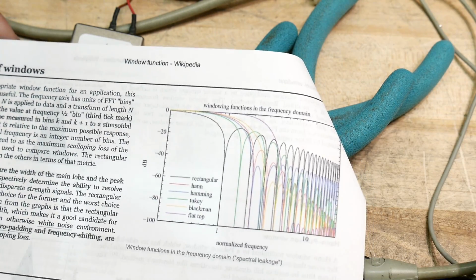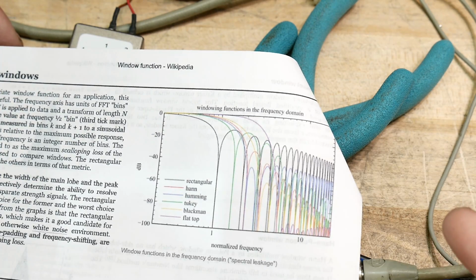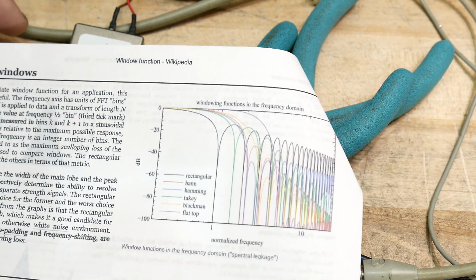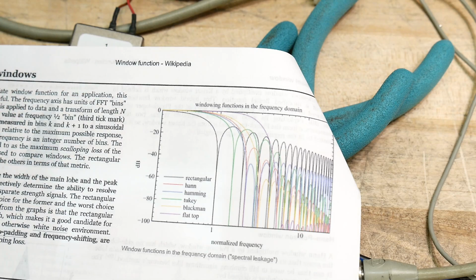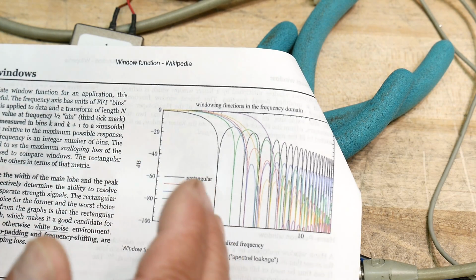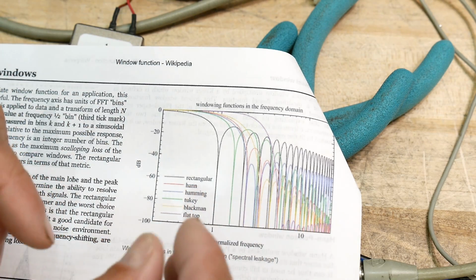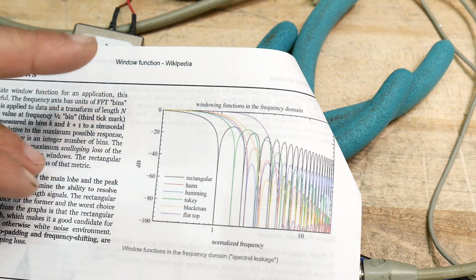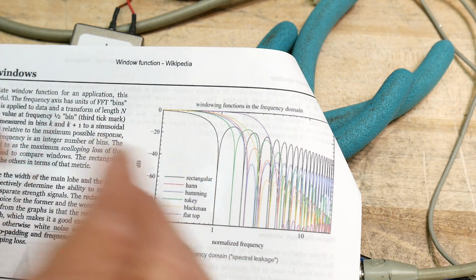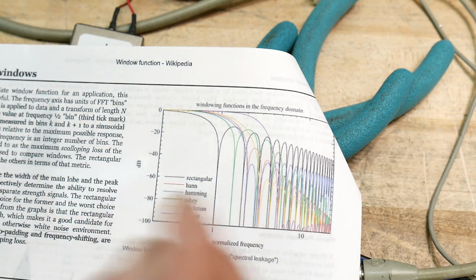frequency responses. So why do you need to use them in an FFT? The basics is that if you do an FFT, you want an infinite number of data points. And you don't. You have a finite set of data points. And because you have a finite set of data points, you will introduce errors. And you need to approximate what happens outside of your data set.